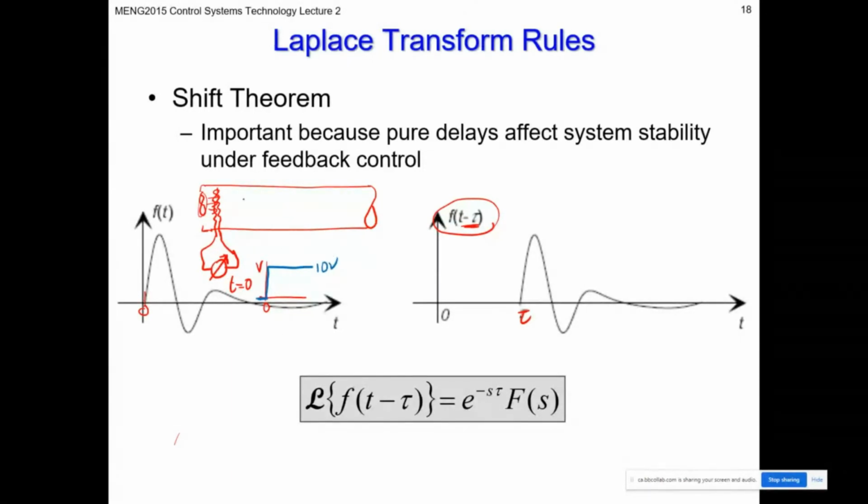And that creates a change in the temperature of the air. So immediately, as soon as that step change happens, let's assume that there's no lag time in the heating up of this element. It immediately goes up to full voltage and to full heat. So from the time when this voltage is applied to the heater, the temperature of the air, the temperature here is T1, it immediately steps up to temperature T2. Now, if the air is moving down the pipe, this is the air at T2. Down here, your air is still at T1.